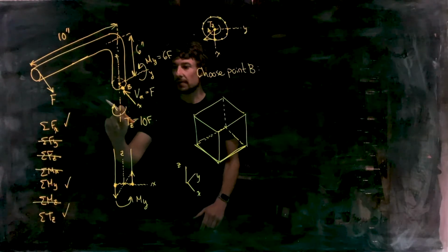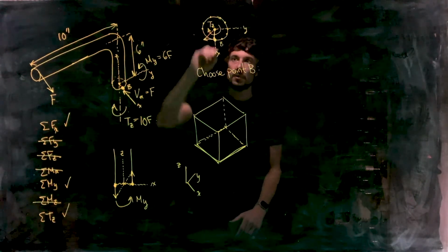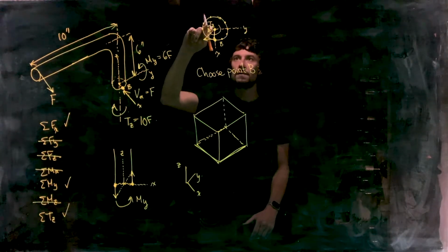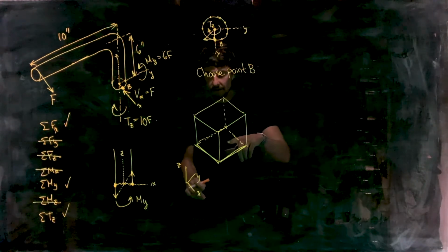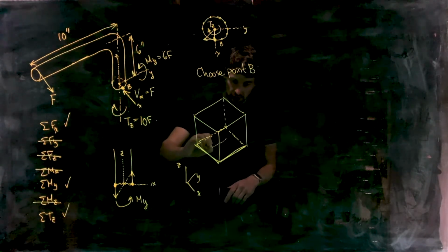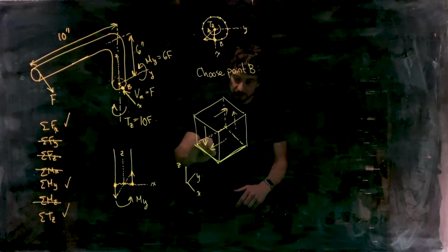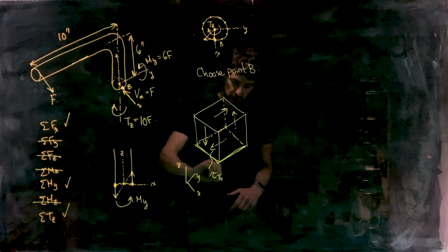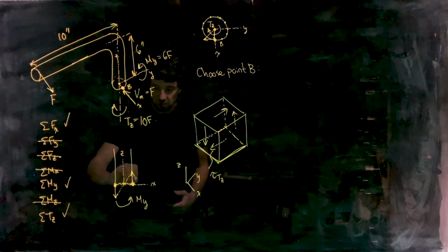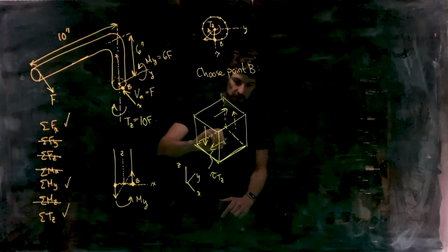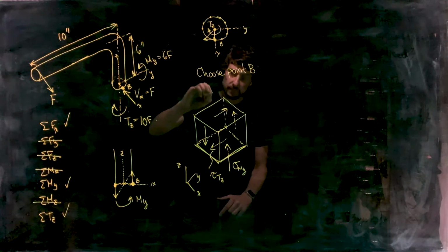Okay, so at point B, from the internal torque, we'll have a shear stress. Here's point B up here, right? It's going to be pointing in the direction of tau Tz and tangent to the circumference at this location. So that's in the negative Y direction, right? So we come to our volumetric element and put a shear stress on in the negative Y direction like this, okay? And one up here, one there, and another one there. So this guy here is tau due to Tz. All right, our internal bending moment, we already said that there'll be compressive normal stress at this location B. So let's go and put on a compressive normal stress sigma due to My right there.